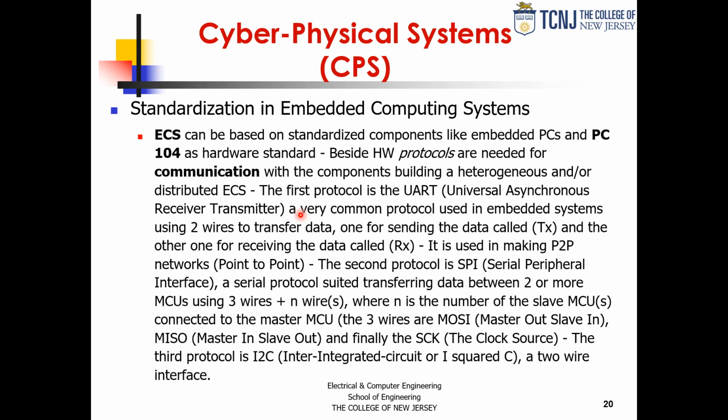And then also we discussed the I2C protocol, a 2-wire protocol that was devised by Philips, before some of that became NXP, and it was devised to hook up and be able to make a network of ICs on a board. So it's an addressable bus where each device has an address, and it supports of course a master-slave arrangement, but also it supports multi-master, so peer-to-peer type communications.